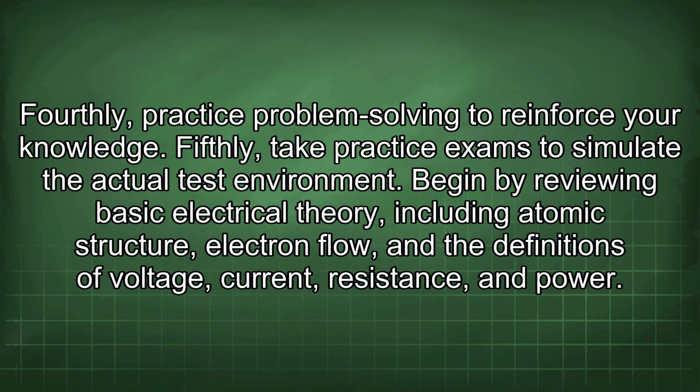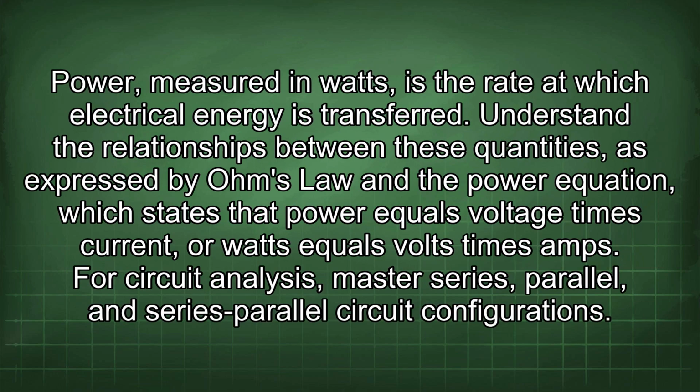Begin by reviewing basic electrical theory, including atomic structure, electron flow, and the definitions of voltage, current, resistance, and power. Power, measured in watts, is the rate at which electrical energy is transferred. Understand the relationships between these quantities as expressed by Ohm's law and the power equation, which states that power equals voltage times current, or watts equals volts times amps.